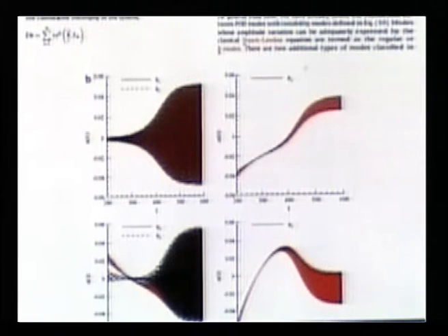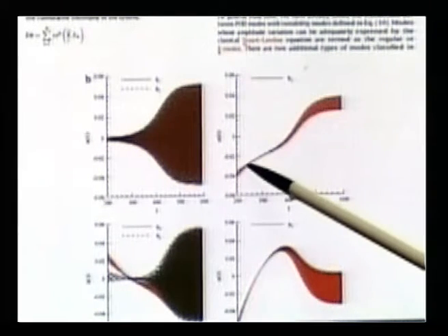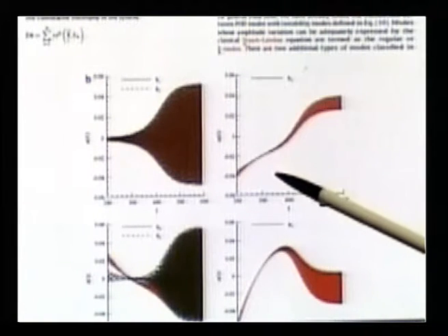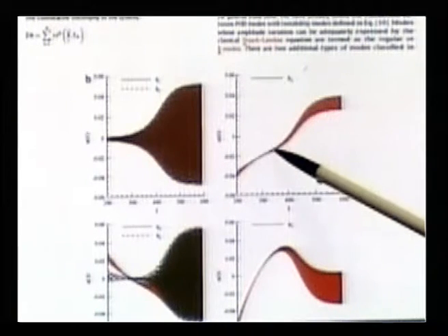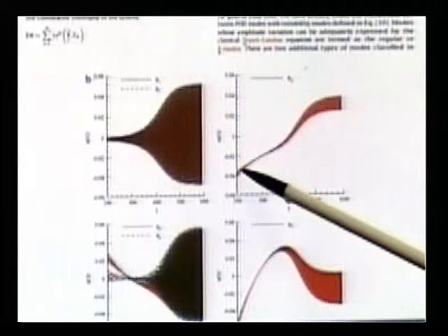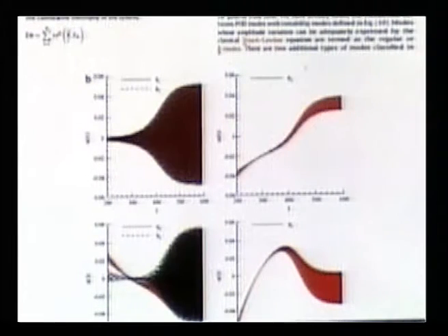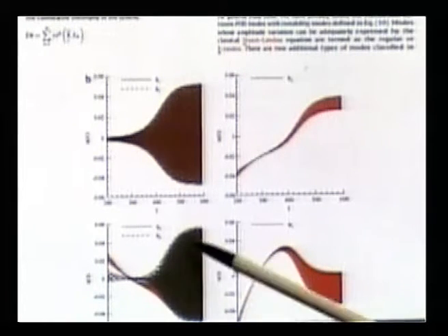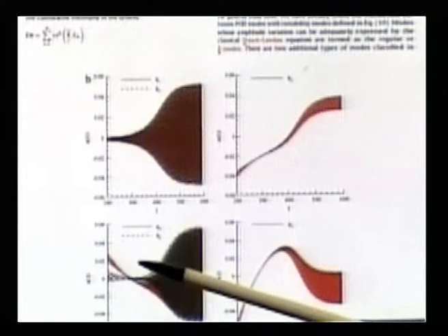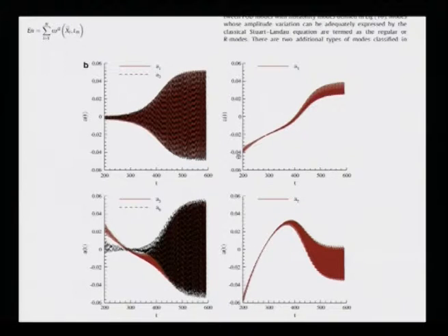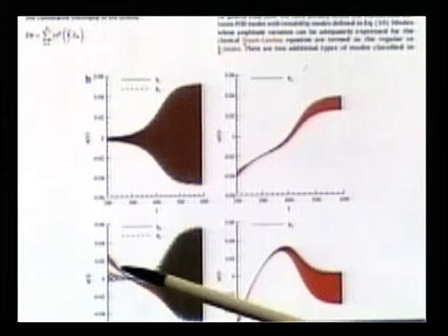And we have the third mode here, which was that shift mode we talked about, which appears singly, and you can see that it does not start off from 0 like flow past a cylinder, because of the strong transient nature of the flow to begin with. So, it starts off with some value, but it does settle down eventually. And this is another regular mode pair. You can see that during the transient state they do not have the pure orthogonality that you expect from POD modes. POD modes are supposed to be orthogonal, but they do not remain so.